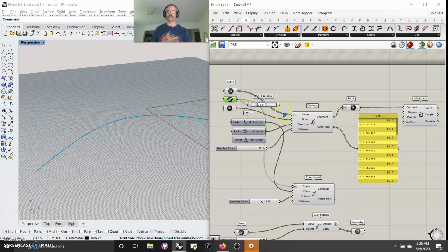If I choose the one curve, which will be easiest for the demo, you can grab a point external to that. You can move that point around, and that will show you how that influences these points. But I thought it was nice to take that curve, and this is an interesting trick: take a Points on Curve, put that in as your point, and start to change that.